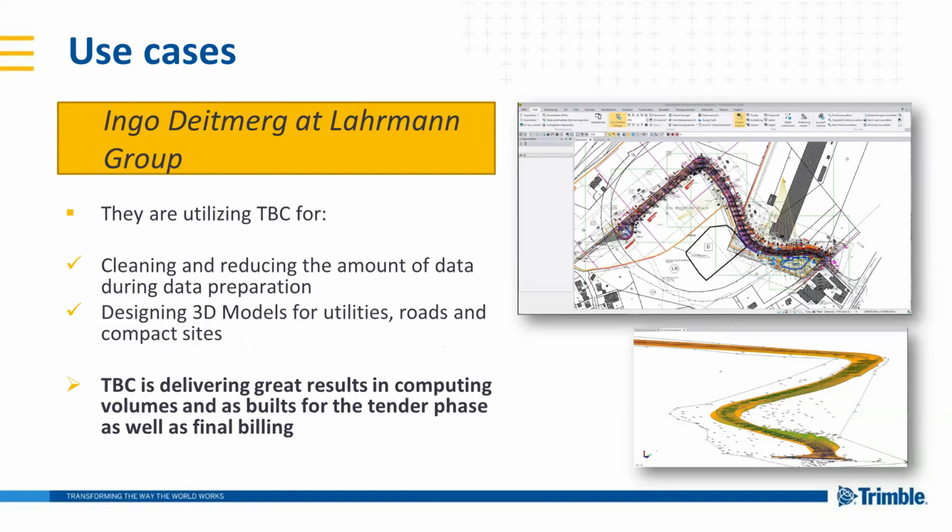Another topic here: cleaning and reducing the amount of data. I mean, everybody knows when we get a DXF from the designer or owner, it's often full of thousands of layers and double lines. They're utilizing Business Center to clean up the whole project and then design the 3D models for their utilities, roads, and also compact sites.